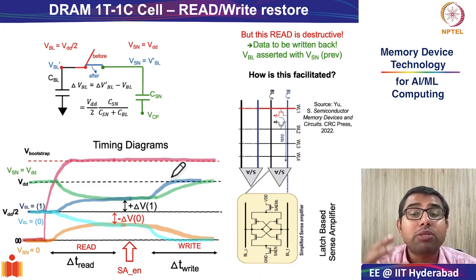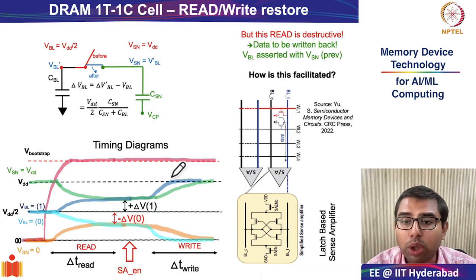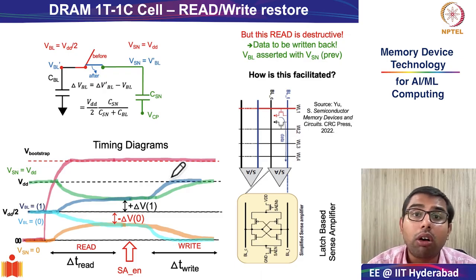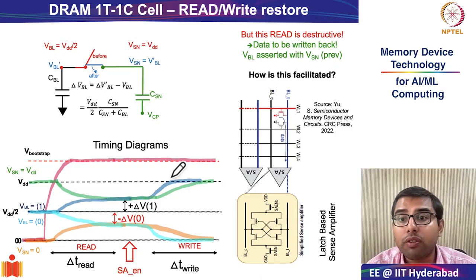Also, the DRAM subsystem architecture, which was this inverted hierarchy of starting from the array, going up till bank, and then chip, then DIMM, and channel, and so on and so forth, which helped us gain a lot of parallelism and try to somehow mitigate the memory wall, which is the big difference in the performance of the CPU versus that of the main memory subsystem.